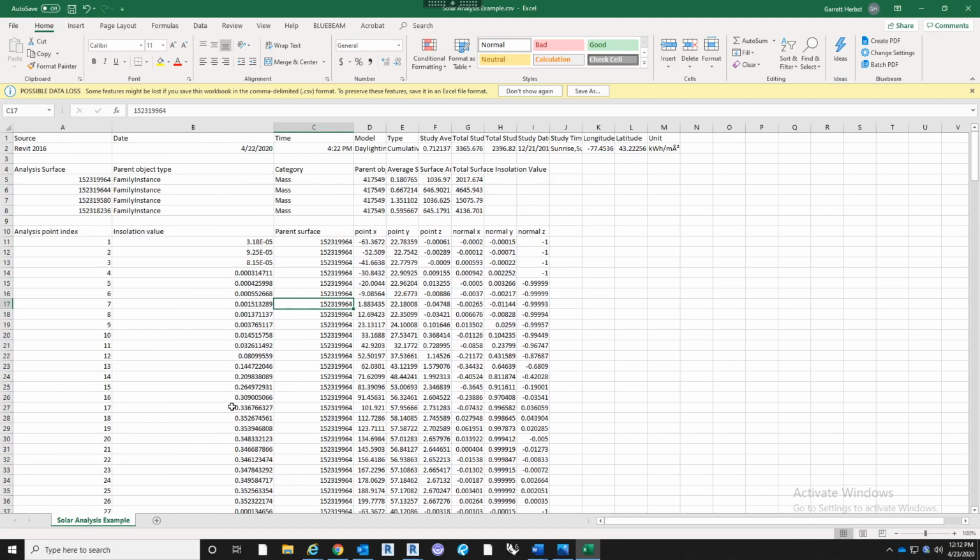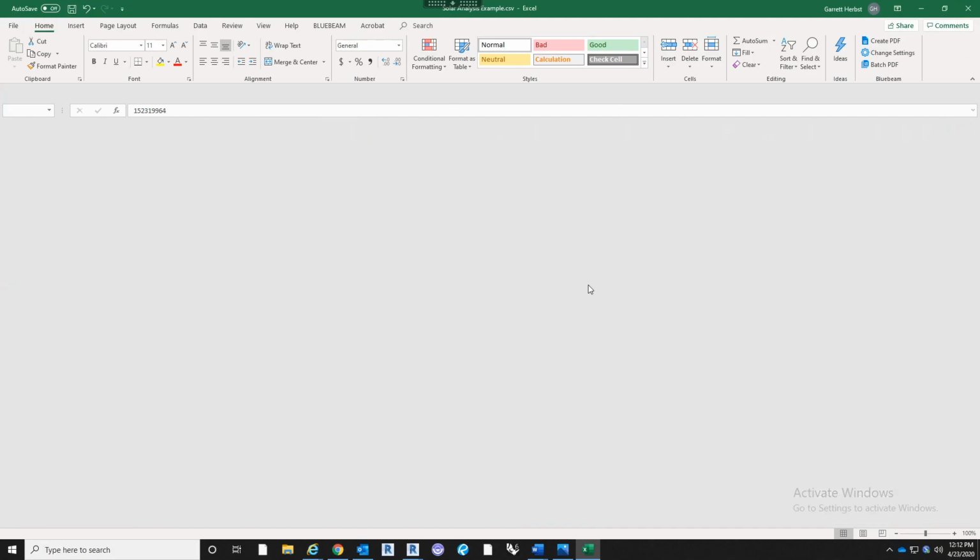Potentially you could, just like we've done in the past, import this into a Grasshopper script, attribute each one of these insolation values and redistribute them to a certain opening percentage or a certain angle percentage, and get a really dynamic as well as a really performative shading device. And that can be attributed to a bunch of different things. So that is solar.